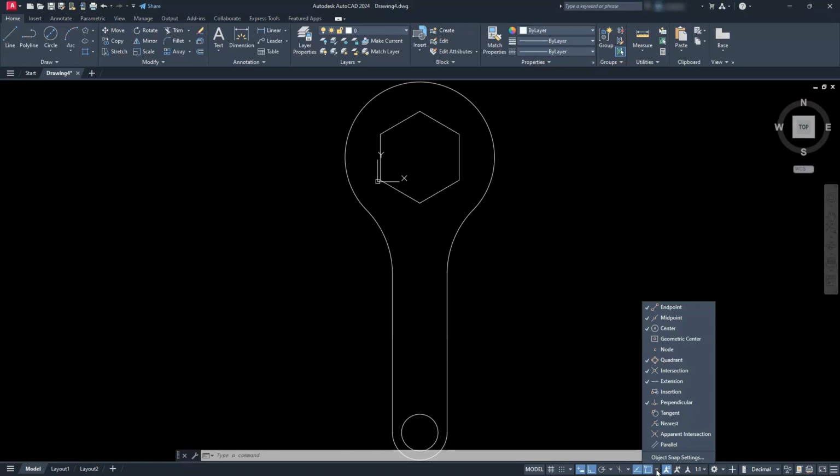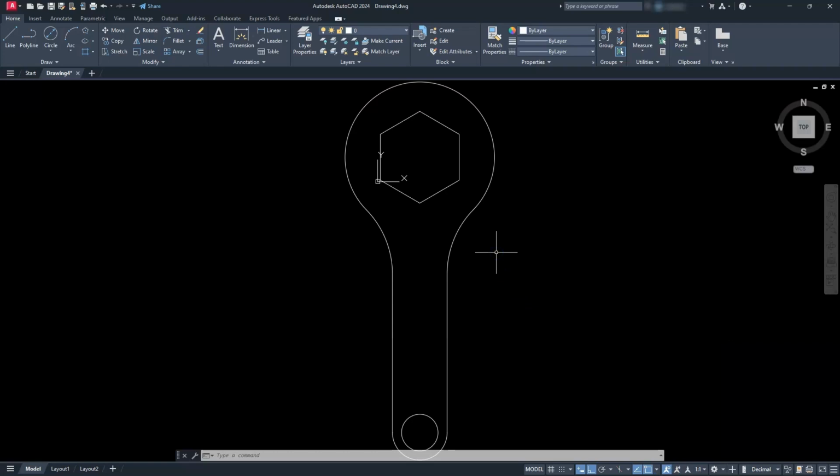Alright, so what I'm going to do here is that when you are dealing with paper space, the best thing I like to do is normally go ahead and set up how my paper space is going to look. Now, I know this is a millimeter drawing or metric drawing. I'm not going to shrink this one down or do any of the other stuff that I would normally do and convert this over to inches. I'm just going to go ahead and put this millimeter drawing on an imperial title block.